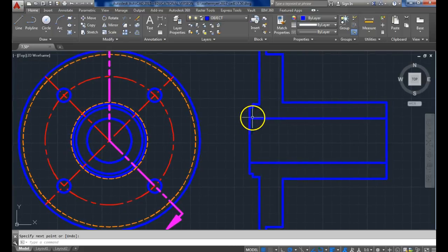Alright, now easy stuff first. There's a couple fillets. This is another one that just kind of gives me the rough rule. Fillets and rounds are all radius 0.12. So if I do fillet, radius 0.12.